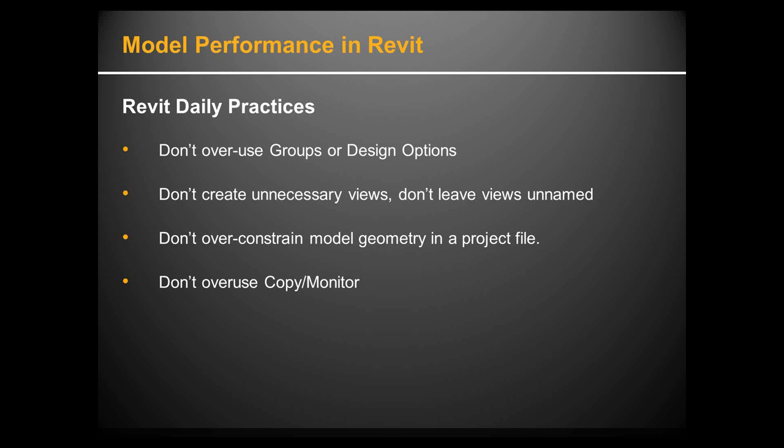Yeah, and one thing you can do is set up a schedule that lists all the views not on a sheet, or all the working views if you were using working views as a specific section or something like that. And then you can go to that schedule and delete all those views. So that'll save you some time and get things done. It makes it easy instead of hunting and pecking and finding those. Yeah, that's a good idea. Schedules are useful. Or schedules can be powerful, even for something like that. You're never going to print that one, but you use it for your own tool.